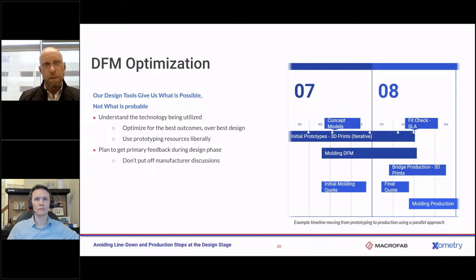Yeah, so when we're using two different footprints, how we do the stenciling is going to matter based on how the larger component is designed. You can't really use, for example, the two parts over each other when there is a big thermal pad, thermal ground below the larger component. That just really isn't going to work. But when that isn't there, and we're not talking about something like a BGA component, but a leaded component, there's typically going to be some height off the board for the leaded component. So we have two options there.